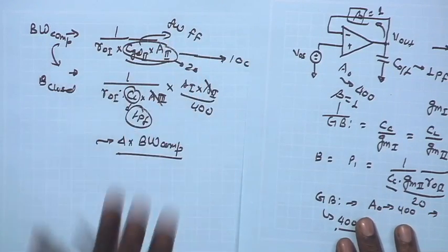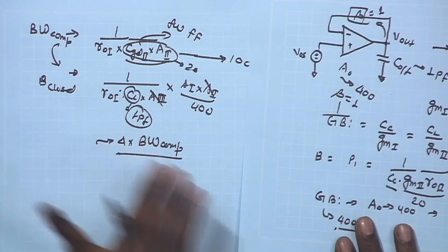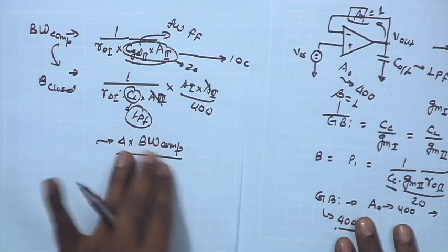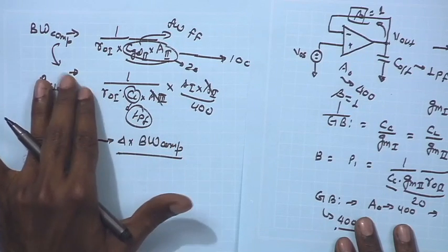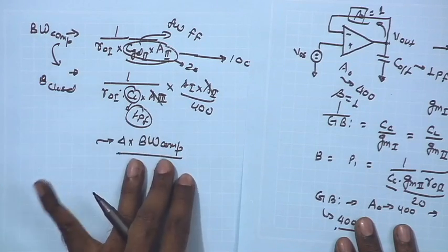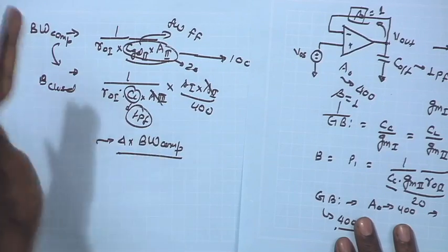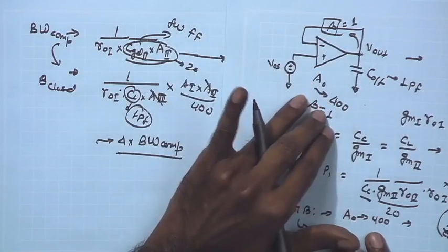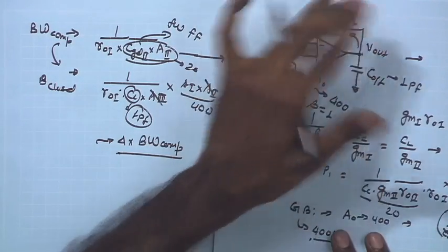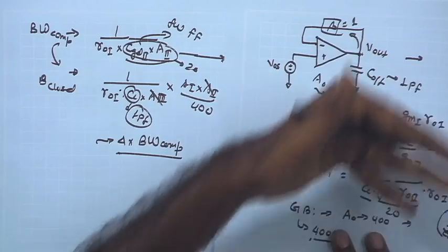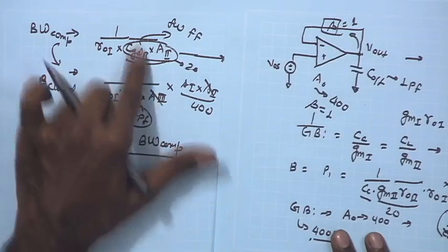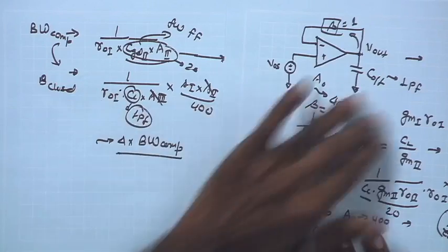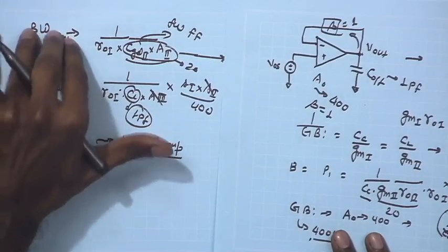Based on these numbers, what we are seeing is that for our design example, the constraint is we are very much within the limit for the closed loop operation of the unity gain feedback, but this is not a generalized case, this is only for our specific case. If you have other specifications, the gain of the comparator being high rather than 400 being much larger, or the C offset being high, that would have a different ratio, and that can make the overall closed loop bandwidth for the unity gain feedback lower than the comparator bandwidth.